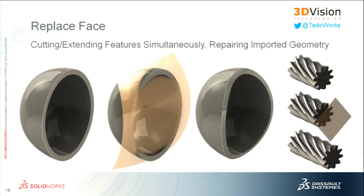Yeah? The replace face surface doesn't have to intersect, but the cut with surface does have to intersect. Is that true? When you did a cut with surface, you have to use it. Yes, if it were a surface, it would have to fully intersect where you want it. Exactly, yeah. The replace face is a little bit different like that. It can see the existing surface, and so it knows the extents to which it needs to extend the other surface that you're replacing it with. But yeah, that's right too. The cut with surface always needs to intersect. That's why it's actually kind of useful to use it sometimes.